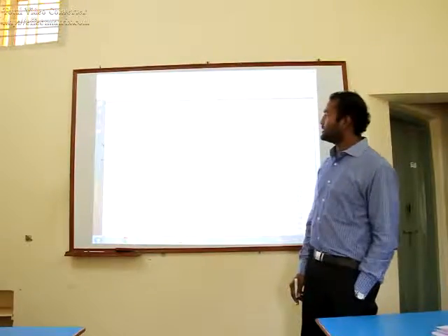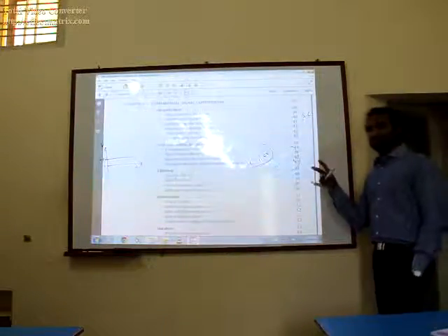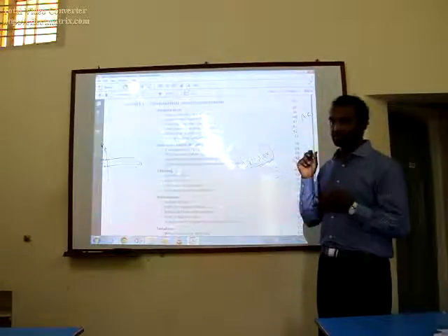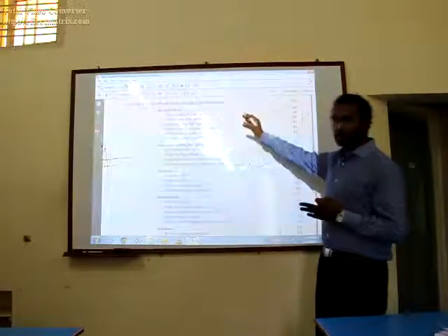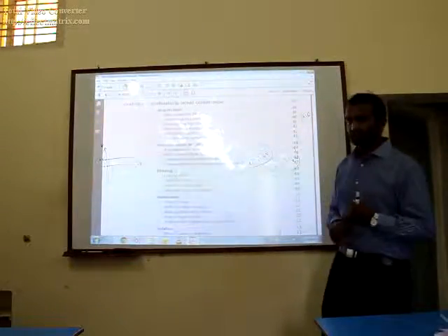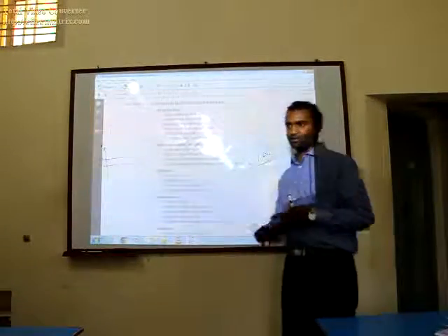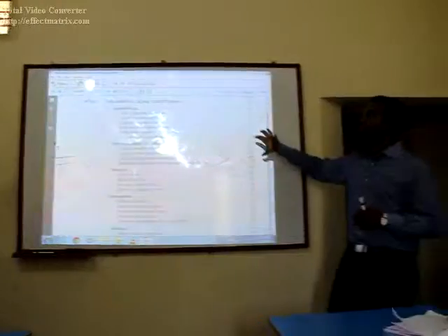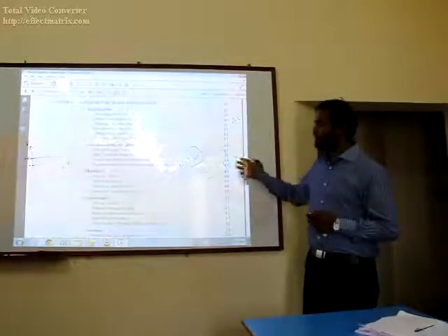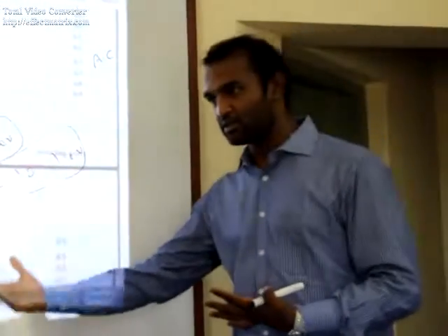The fifth chapter over here is fundamentals of signal conditioning. Whatever points I mentioned for signal conditioning, right from the stage of amplification, filtering, and processing all this data, we have all this. When is isolation required? When is attenuation required? All these factors which are required are called signal conditioning. Can you go to the next? In that, again, there are three forms based on resistance, capacitance, and inductance.